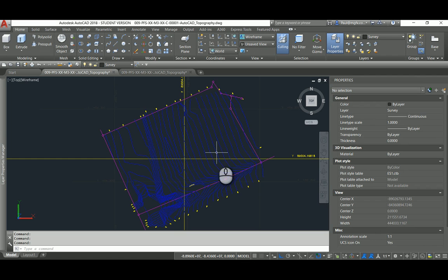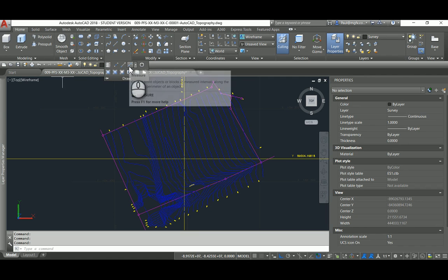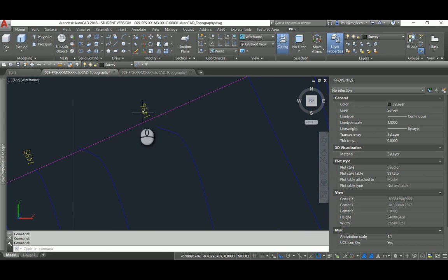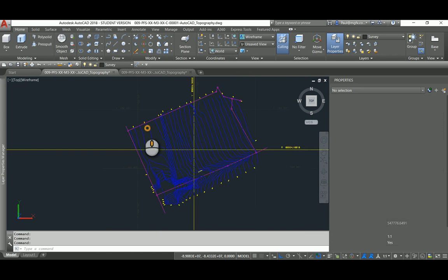So far so good. In this drawing those contours were included, and what I did was I used the measure tool to go and divide those contours up into points, after which I extracted the data from the points to give me a points file X, Y, and Z. That's also why you'll see that my points file corresponds to the heights annotated here in meters.